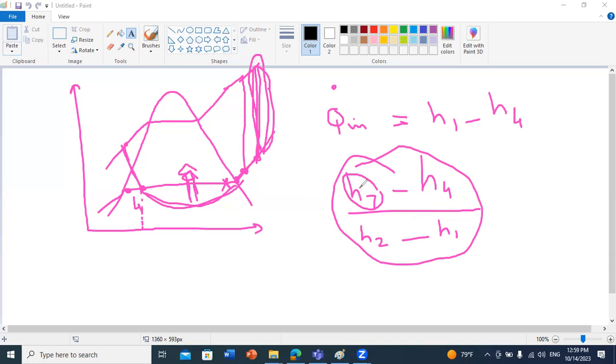It's good maybe to increase it a little bit because this will increase the Q dot in, but at the same time, it might increase H2 a lot, so I should check for this. While point 4 is just affecting this term, Q dot in. So a good strategy will be to condense more in order to decrease the quality at the inlet of the evaporator. So you can do this analysis, for example.